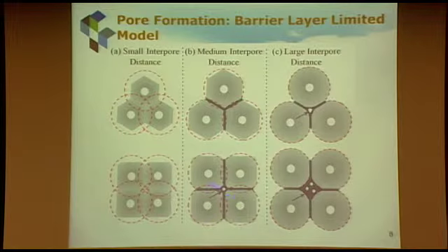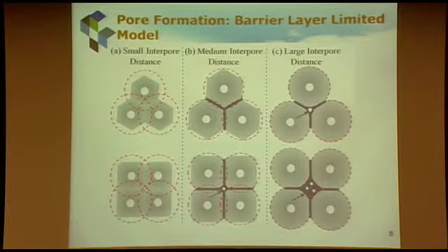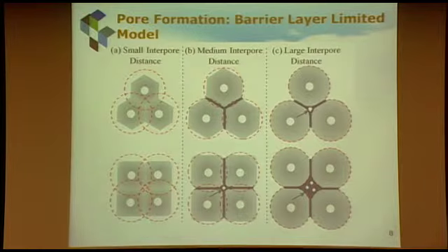direction. So this distance is a lot further than this distance, so you start seeing the new pore appearance much earlier. And then when you have the same pore distance, you already have a big region here, so the new pores, you start creating more than one, and then they don't arrange nicely. So this actually goes back to the original anodization process.